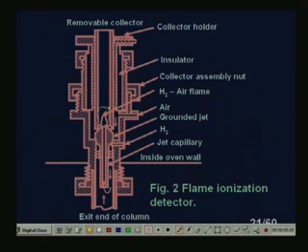Now, this is mounted around half a centimeter to 1 centimeter above the flame tip, and across the two electrodes a high voltage of 400 volts is applied, and this lowers the resistance across the gap and causes a current to flow. Normally, an external bucking voltage is produced to balance the potential generated by the ions and free electrons generated in the pure hydrogen air flame. This ensures that a net current flows only when ionized materials enter the gap, thus enhancing the differential sensitivity of the detector.